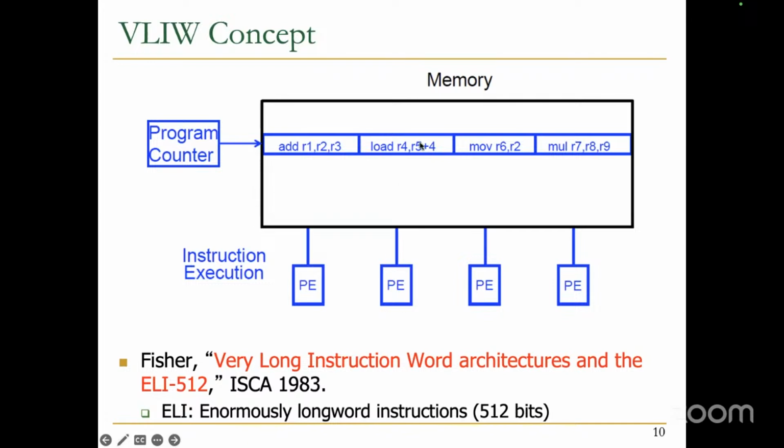Then the compiler knows I can put a load only in this position in the instruction, so that when the hardware fetches it, it directly has a wire and routes the load to that location, as opposed to having some sort of shuffling network where you need to shuffle instructions from one location where you fetched it from to the processing element that may be far away. So hardware actually gets simplified for multiple reasons, as you can see, not just dependency checking, but if you actually expose the structure of the pipeline, where are the processing elements, assuming they have differences between them, then the compiler can actually help you reduce the hardware cost.